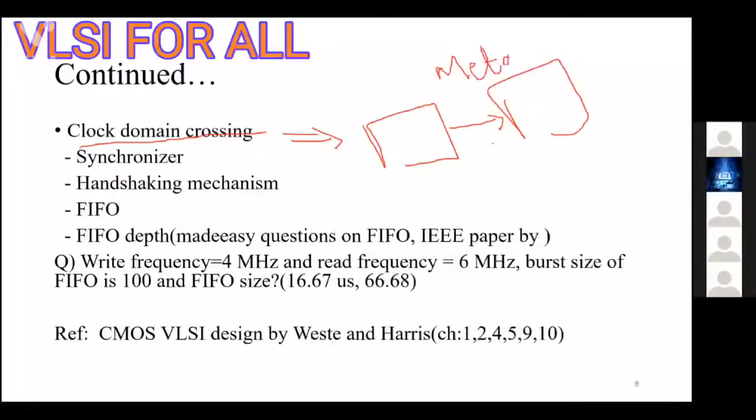So the input may fall in the setup and hold window. Now, if the input falls in this window, then the circuit output will be going into metastability.